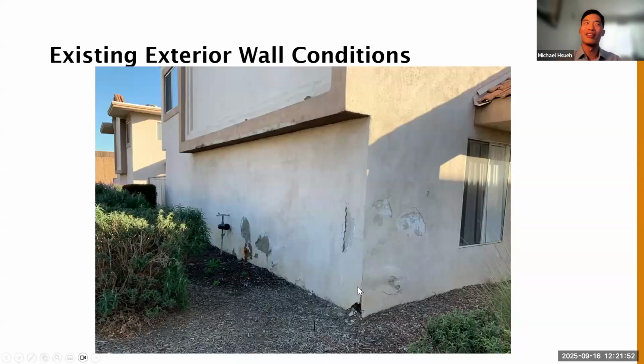And I think the big thing that was a huge headache for the team in trying to figure out what to do was that the stucco and the drywall at Corona had asbestos. So you couldn't just rip things out and drill and whatever. You had to do abatement. You had to have a plan for that. You have to have these environmental contractors coming in very specific phases with all the work, not just the enclosure that I'm focusing on here, but also the mechanical and electrical upgrades. So that was a major component of what we were looking at from the exterior.